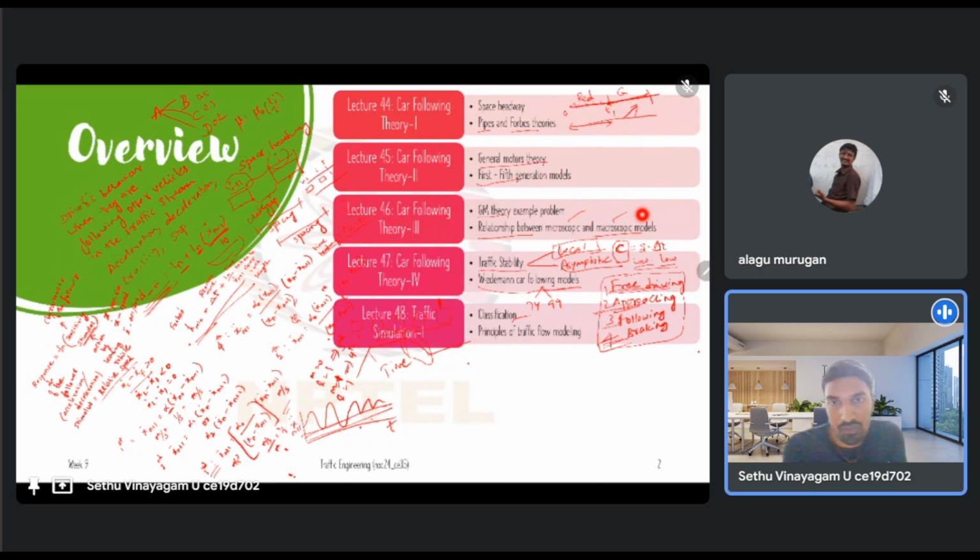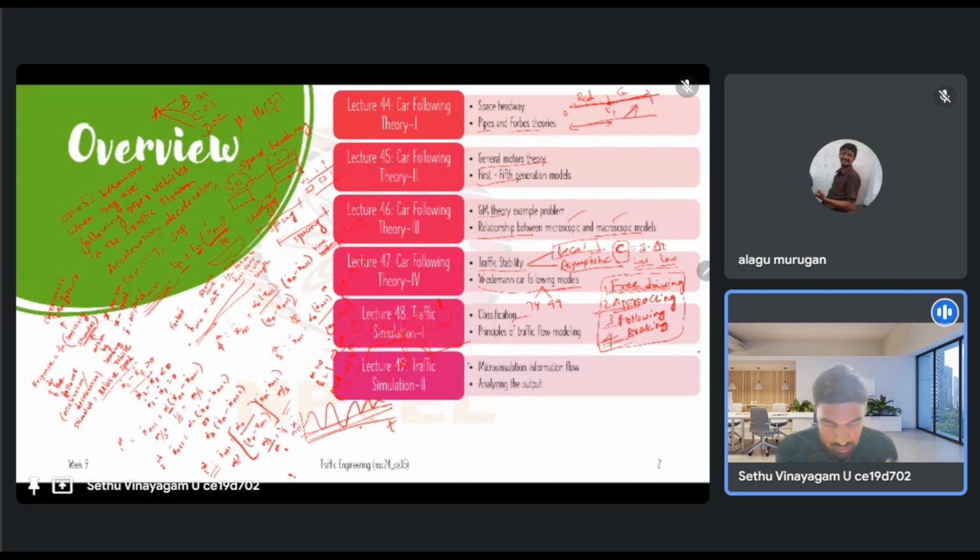What we choose for our study depends on what is of interest to us, right? If our interest is to look at system level changes, then we need not look at each individual vehicle, and we look at the macroscopic scale, what happens to traffic flow for different lanes, right? Which lanes are congested or not congested. We do not have to look at acceleration and deceleration profiles of individual vehicles. Depending on our application or intention, we choose the principle of traffic flow modeling accordingly.